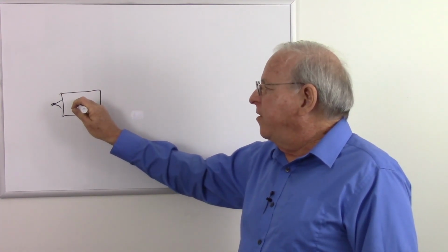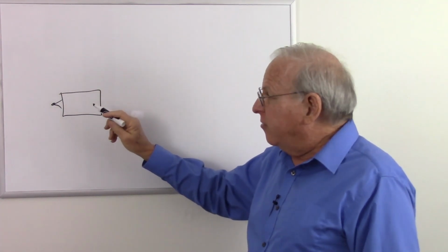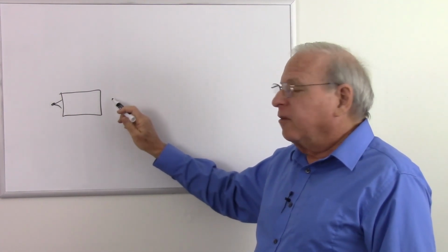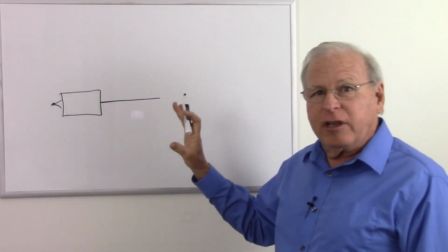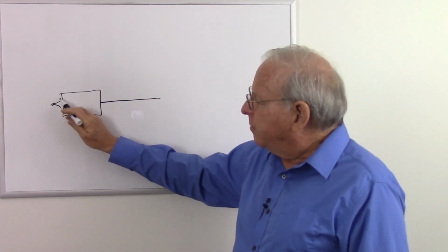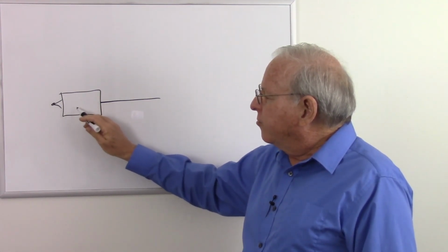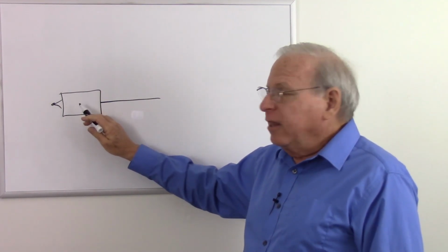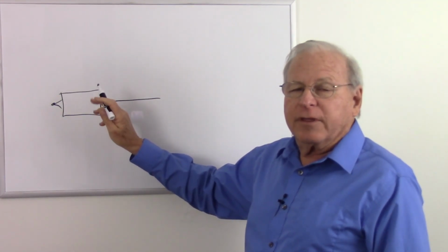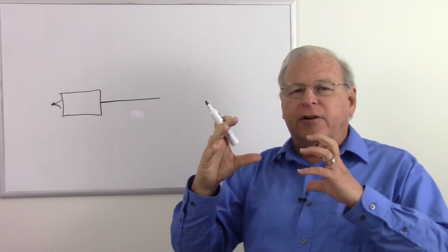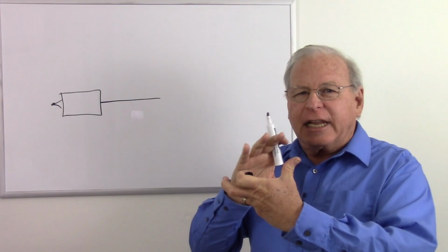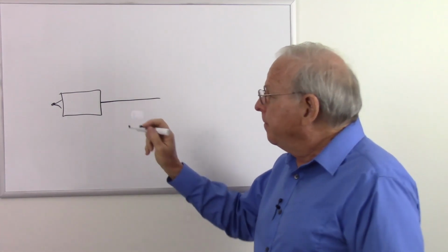And so we have some very simple circuitry that would linearize that so that if the temperature doubles, the voltage output would double. And let's take a look at the output of that. We have a single wire, so we're starting off with a simple temperature sensor and some pretty simple circuitry that would linearize the output of that. That could be done with a diode or a transistor because they are nonlinear. You put one nonlinear thing working against something else that's nonlinear, you can end up with something that's linear.